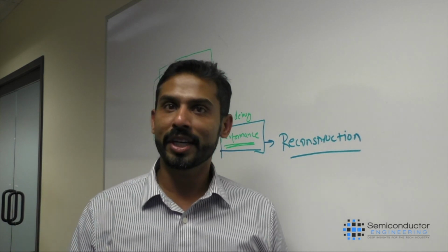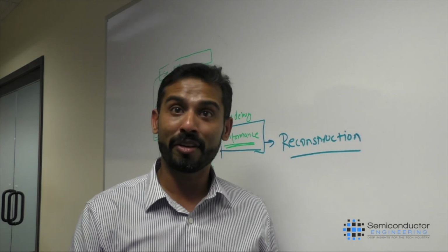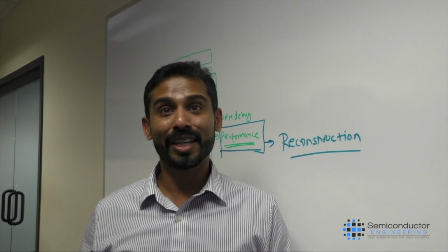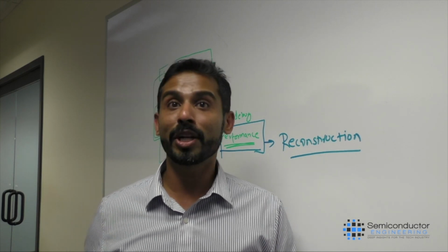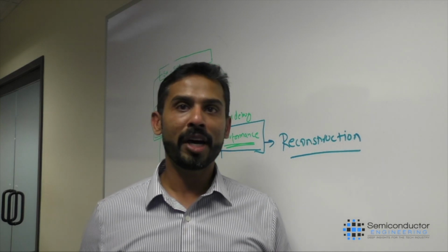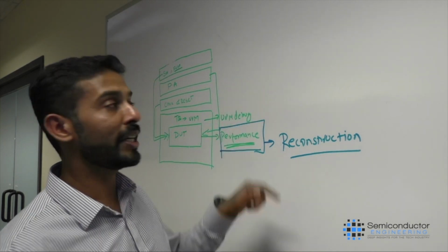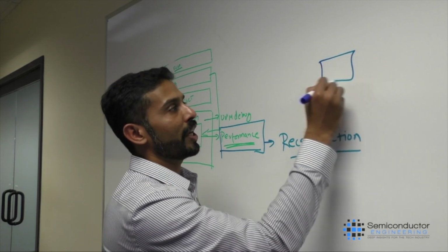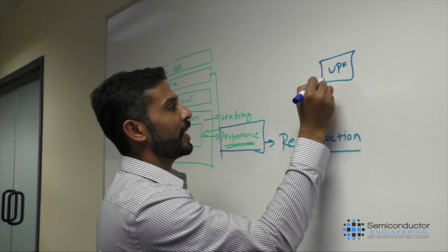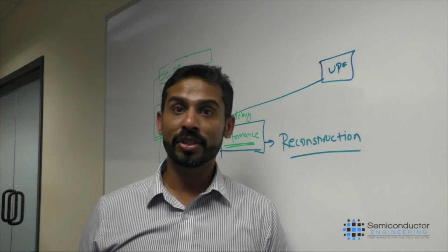So power becomes critical, whether you are designing a massive processor with a couple of power domains, or a small IoT device with multiple power domains turning on and off. The interesting thing about power is it's not baked into the design under test. The power intent comes in from UPF. So UPF is passing the power intent into the design under test, the RTL.